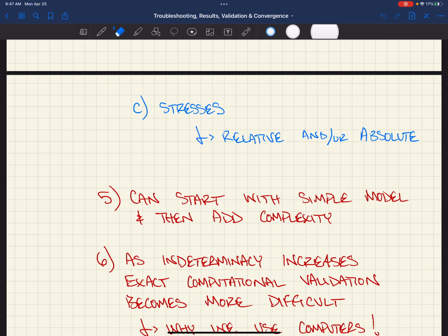So maybe you look at if you had a building and it's on a very regular grid system, which a lot of multi-story office buildings are, maybe it's 25 foot or 30 by 30 grids. Okay, you pull out one of those grids and then you start just validating a model just on that single grid. And then you can copy that through and then do some other validation as you go through. So you can feel really good about that simple model and then extend it off.